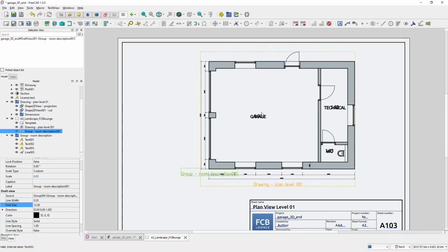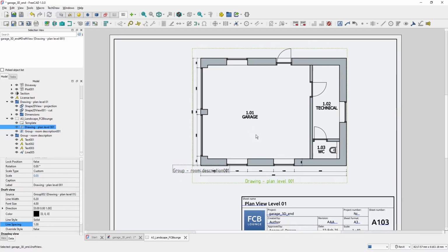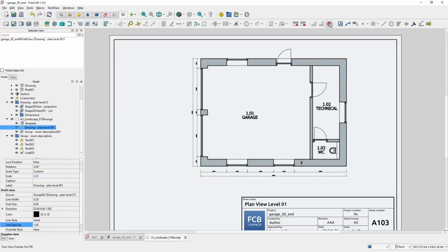But you can still see the problem that the text is kind of meshed up when there are two lines in one text object, and this is again set up in the drawing properties and its line spacing value, and if I set it to 5 or 6, this should be okay. So the drawing is moving on nicely. You don't have to be worried about these labels, because if I turn off frames, this is how it will look on the page. So these are only working frames.